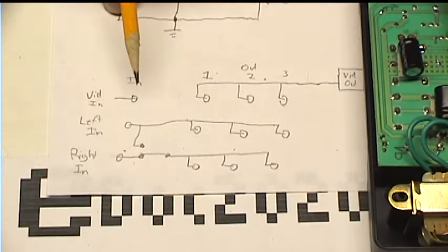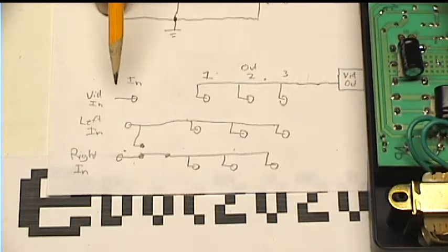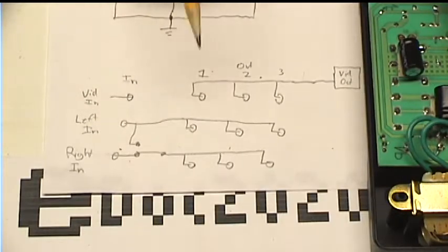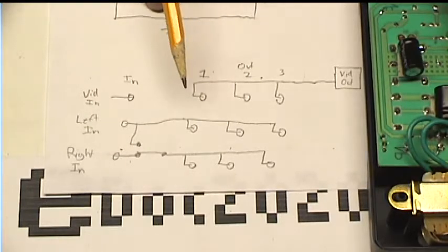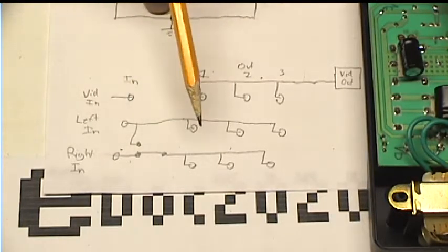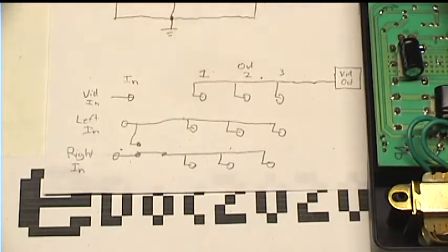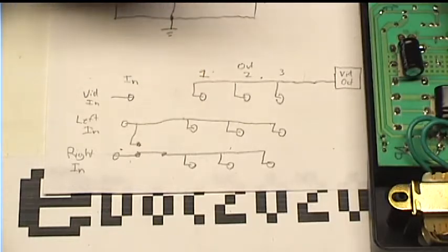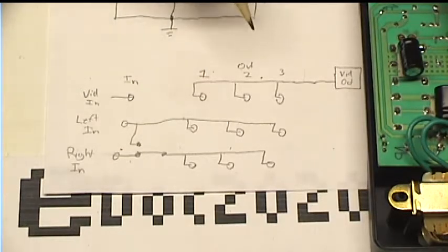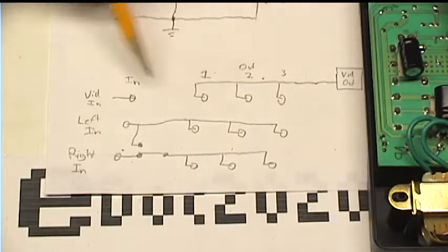And there's also an issue of the cable impedance, which is a topic I don't understand too much. Basically, if you have a 75 ohm cable, it needs to have a 75 ohm resistance at the end, or else you'll get strange signal reflections when you deal with high frequency signals such as video. So that's why you need an amplifier on the video side.